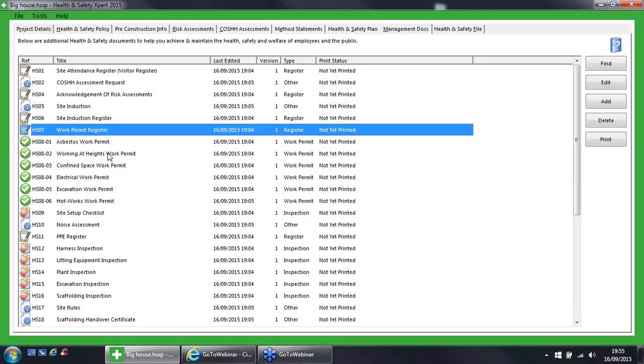Okay, you can also control the times of risks. You might have that you only want particularly risky things to happen on such and such hours because you know that there are other people on site to help in case there is an accident. Okay, so a permit system is a very good way of controlling it, especially if you have a lot of subcontractors or irregular workers. You can basically say to them, if your name is not on that permit, you cannot work in that area on those tasks. It's an excellent way of reducing accidents and making your site more safe.